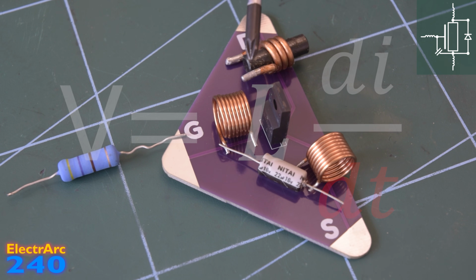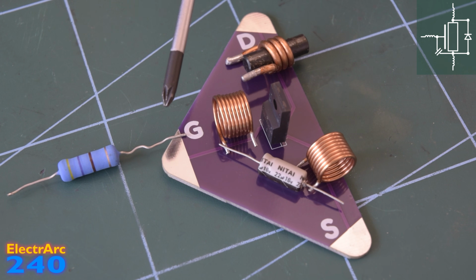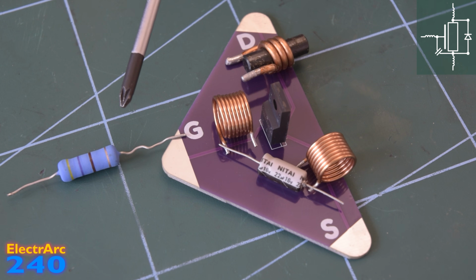So in a lot of circuits, especially if you have a well-designed gate drive, the gate resistance is actually used to tune this overshoot. It's not to do with protecting the gate. Cool people even have 2 separate gate resistors, one for turning on and one for turning off. This is because it's often the case that one can be faster than the other for the same level of overshoot.